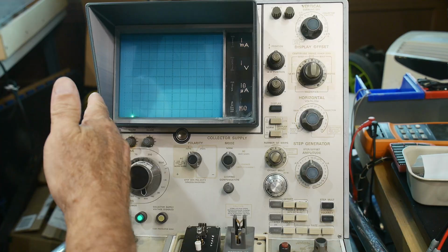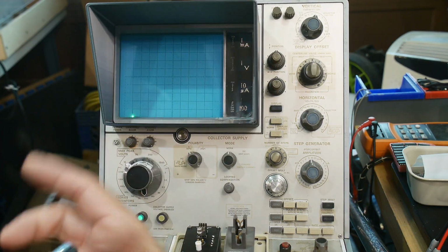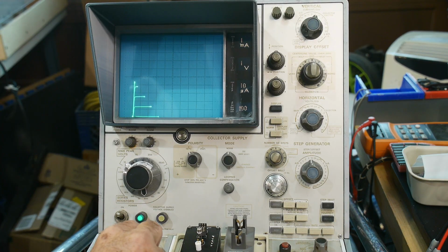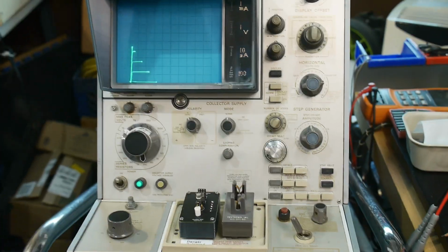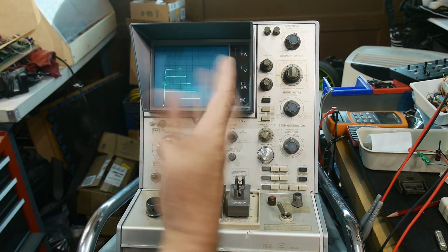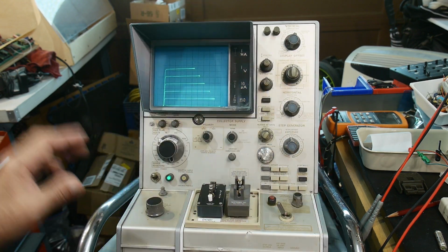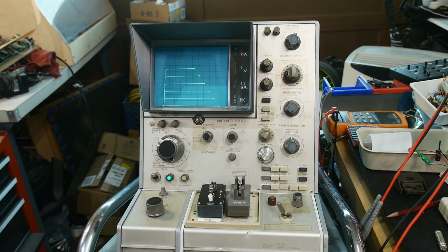Okay, so the amount of voltage on that resistor, on that very, very top, remember the output? That's this knob here. Oh, can you see that? You can't see that. That's this knob here. This knob sets how much voltage is going to be on our circuit. And I'm going to set it to 10 volts, okay? So here's where 10 volts is. So I'm putting 10 volts on that resistor, and I'm getting this picture.